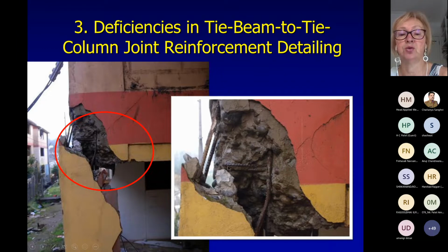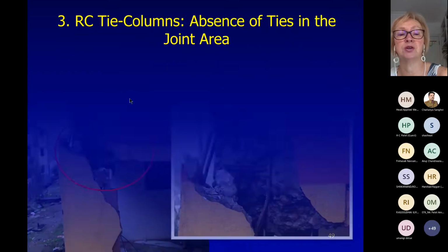It is very critical at the end to have horizontal bars from the tie beam going around the bars in the tie column. Even though it is not a moment connection, the joint detailing is important because once shearing of a tie column happens in that area, then this joint area also becomes vulnerable in all cases. But that is at ultimate stages of behavior, when there is a really significant major earthquake and the walls, the structure, are exposed to very high shaking.